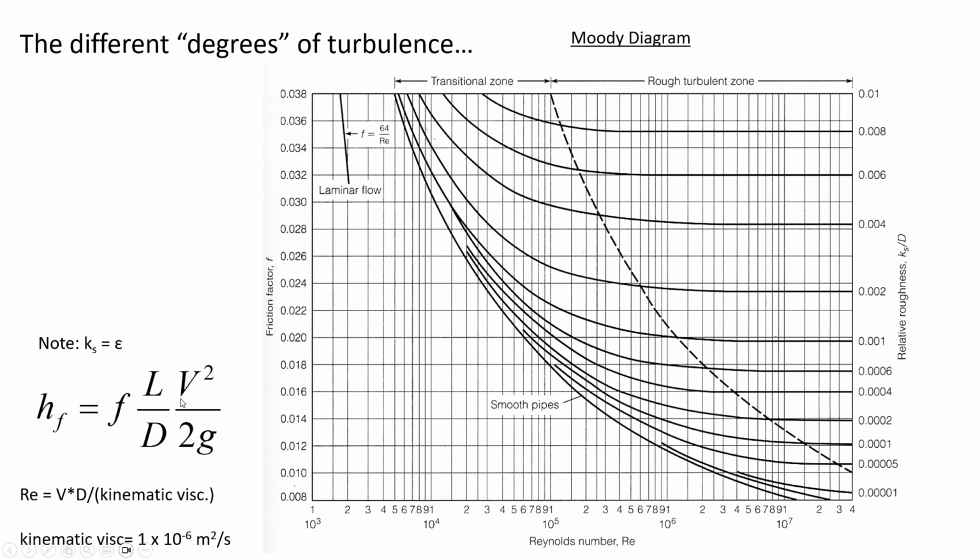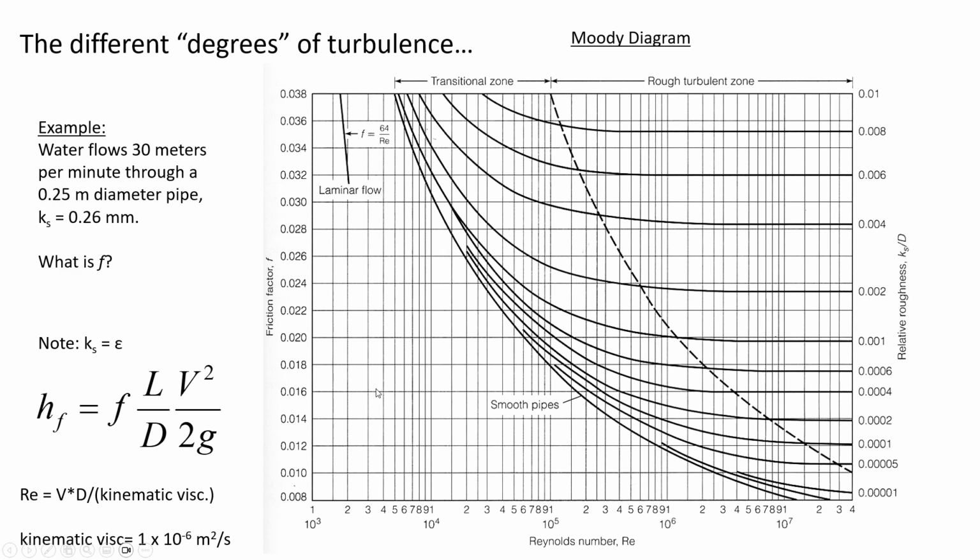So if we know what's the speed, if the diameter is changing, then V1 and V2 will be equal. But the velocity through the conduit, and then some factor f, a friction factor that's going to take into account both the flow conditions, the material type, a variety of factors. So I wanted to just revisit how we calculate the friction factor f using a Moody diagram.